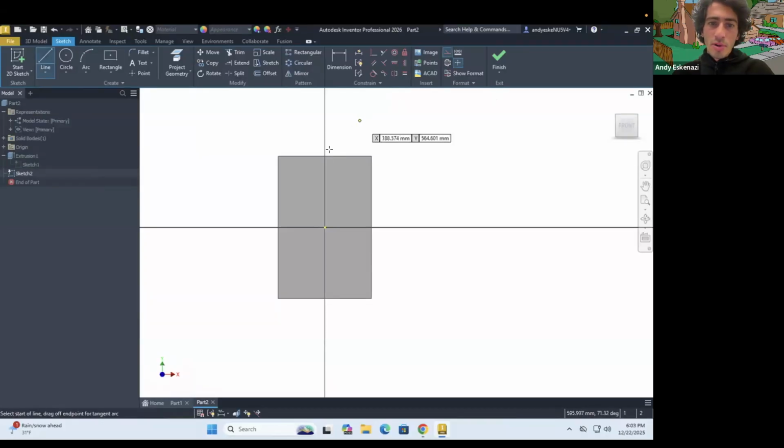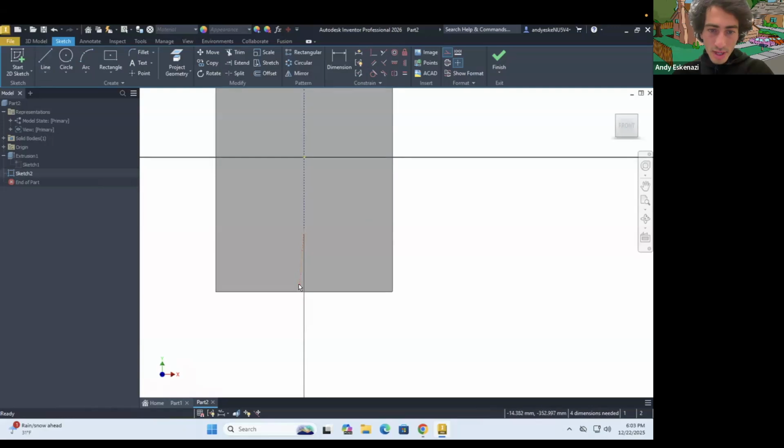We're gonna do multiple construction lines, and you'll see what I mean in a second, because I want these 2 points that I'm drawing right now. So I'm gonna click on that point, control that point, I'll make that coincident, then that line and that line, I'll make it parallel. And then I'm gonna start putting some dimensions to this.